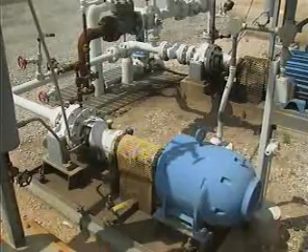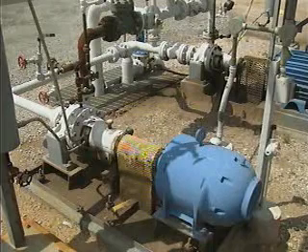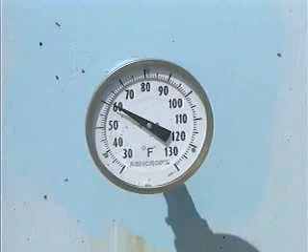Temperature also affects a lubricant's viscosity. If wide, rapid variations in temperature are involved, a lubricant with a high viscosity index is usually needed. Temperatures must not exceed the lubricant's flash point and fire point. On the other hand, temperatures must not be lower than the lubricant's pour point.